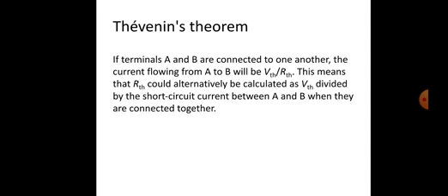A zero valued voltage source would create a potential difference of 0 volts between its terminals, just like an ideal short circuit would do with two leads touching. Therefore, the source is replaced with a short circuit. Similarly, a zero valued current source and an open circuit both pass zero current.